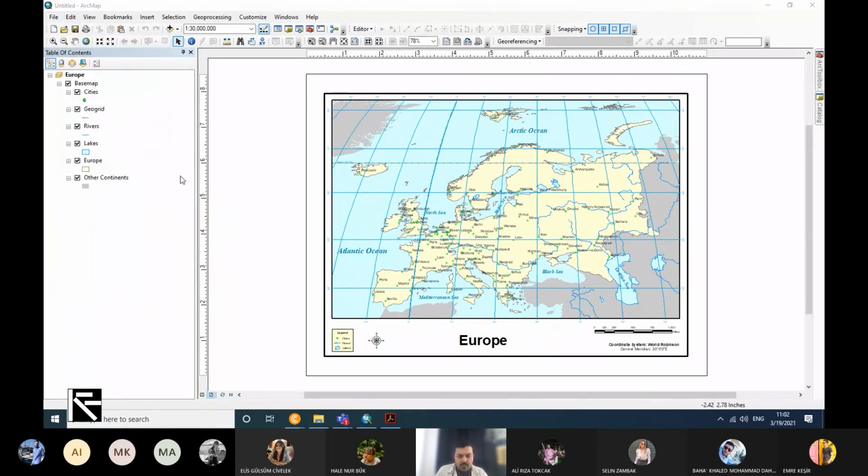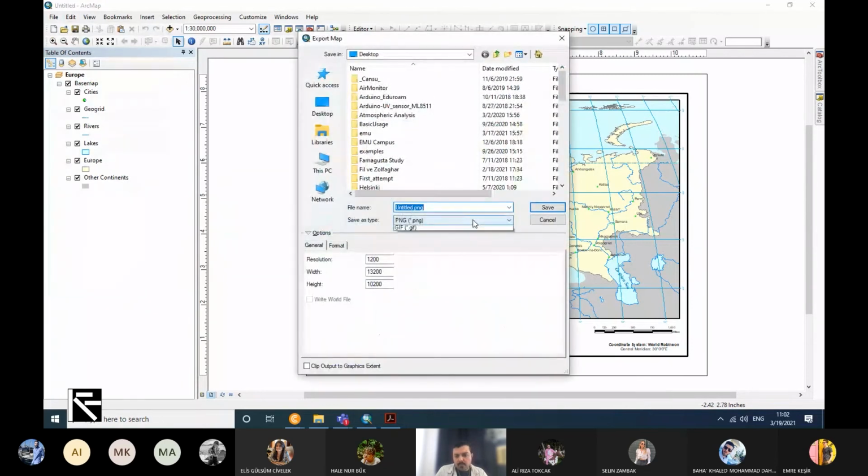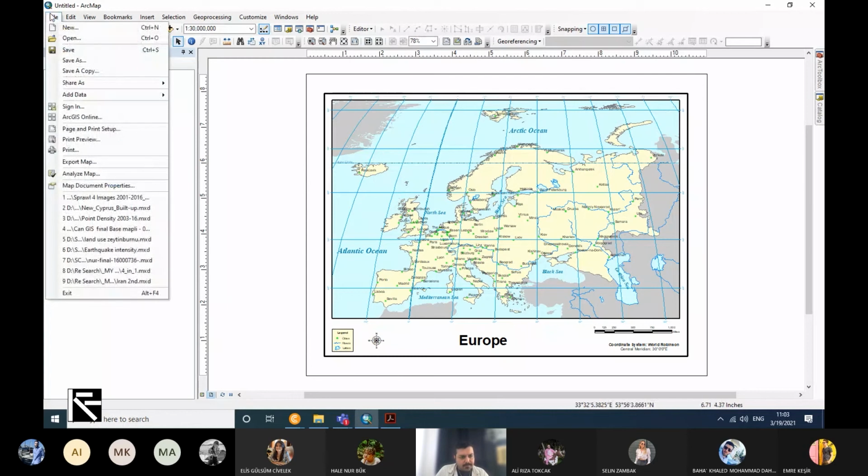At the end, you need to export your map to any of these files: EMF, EPS, Adobe Illustrator, PDF, SVG, bitmap, JPEG, PNG, TIFF, or GIF. Also, you are able to change some DPI, pixel resolution, format, color mode, 8-bit, 24-bit, 1-bit, background color, and transparency. These are easy things. If it's not open, you just hit the option and get it from here.